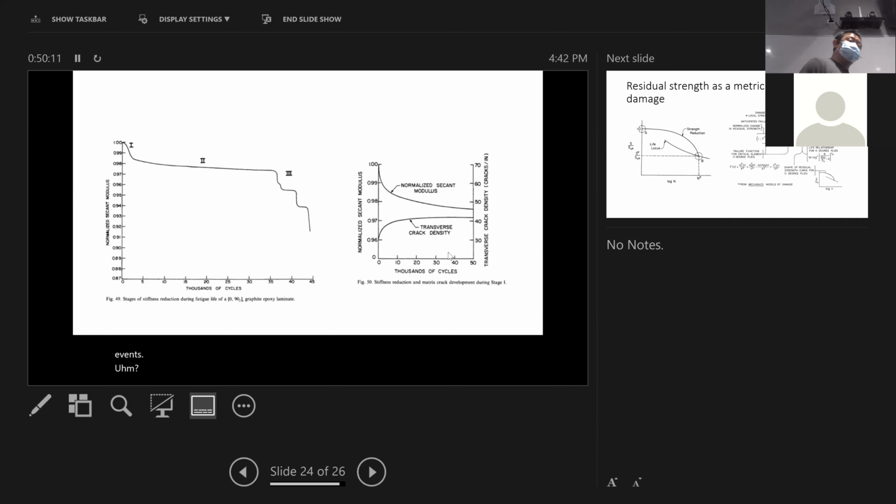And that indeed is a technique people apply to some of the civil structures. Not necessarily composite, but similar to composite, like the cable-stayed bridges. There are many cables on the bridges. Those cables are actually listened to by these sensors. When that fiber starts popping one by one, in an accelerated fashion, that means the bridge is about to go. So the same technique can be applied to composites as a way of monitoring.